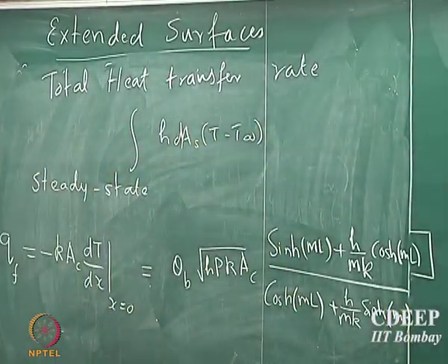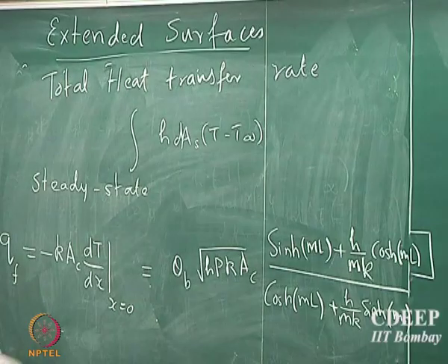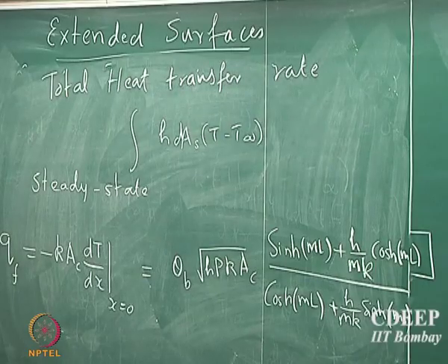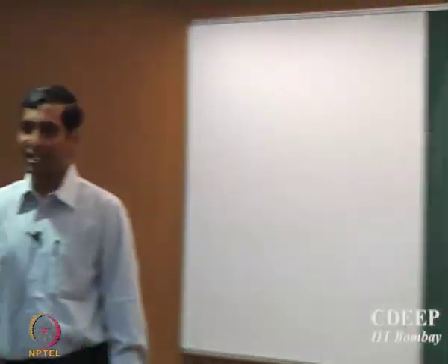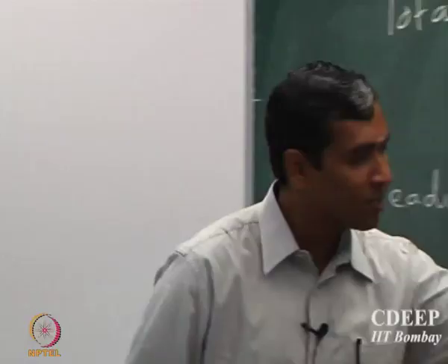Okay. So, that is the total amount. Note that it is the total amount of heat that is transferred. The local heat transfer rate is not constant. Remember, when we discussed the resistances, that whenever there is heat generation or heat loss at a local location from the solid that you are looking at, the local heat transfer rate is now going to be a function of position. And in fact, that is sort of alluded to in this expression.